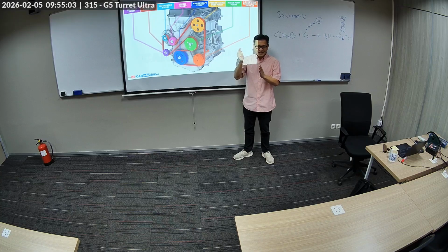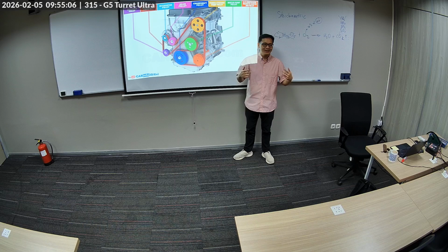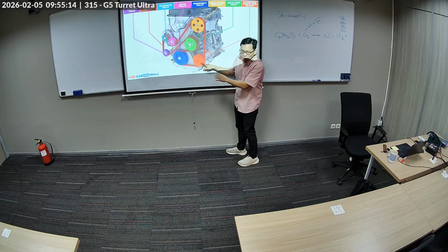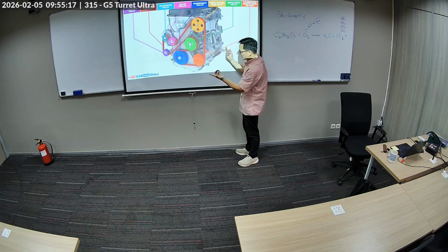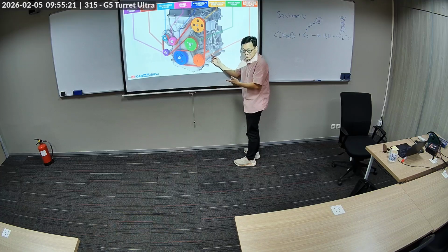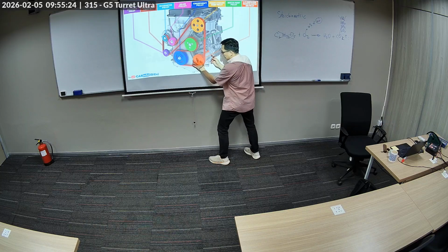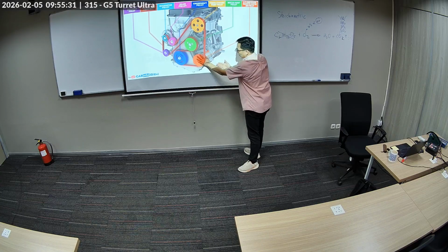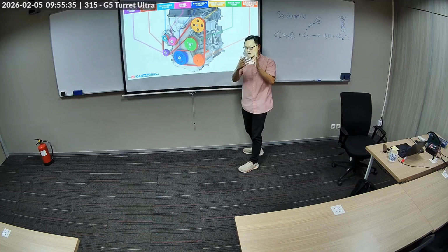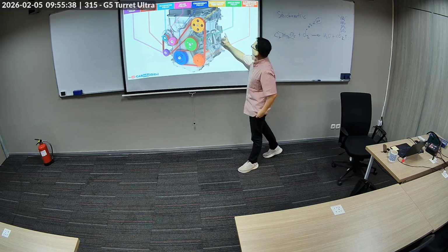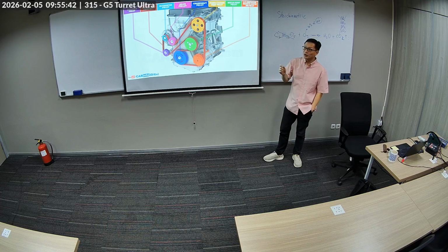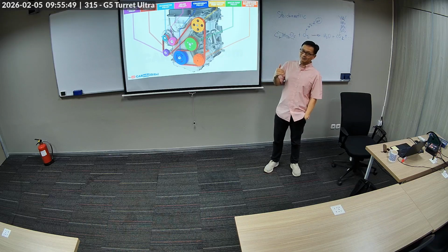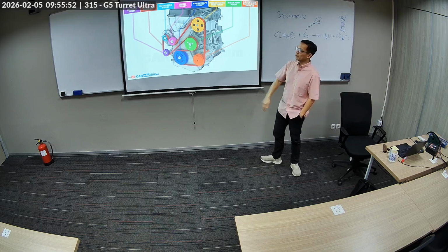If you hear the clicking sound, click, and then the fan starts to sound, and your AC is cold, that's your AC magnetic clutch. The way it works is basically this pulley is always turning because this belt is spinning all the time if your engine is on, right? But the compressor might not be on. And so when this thing is energized, you basically join the two plates between the pulley and the internal plate, the rotor, and then it spins together. So the electronic magnetic clutch is how you control the compressor to be on or off. Because once the refrigerant reaches a certain pressure, then you disengage the clutch. And then you engage it again once the refrigerant pressure drops.